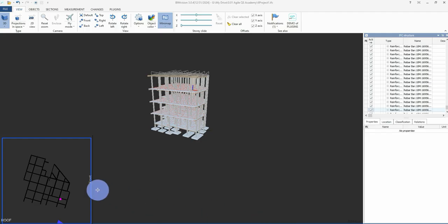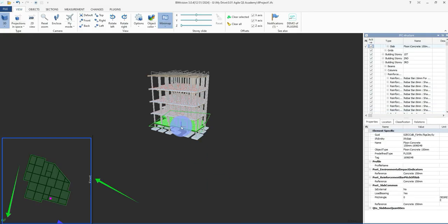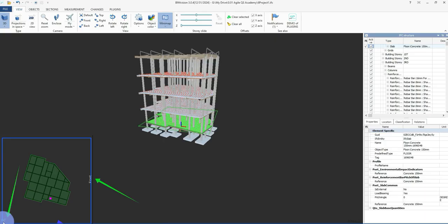First it gives you the direction, which is this front. Second, it gives you the location, which is on the roof, meaning our cursor is now on the roof. Now, when we click on this item, as you can see, it is showing ground floor.